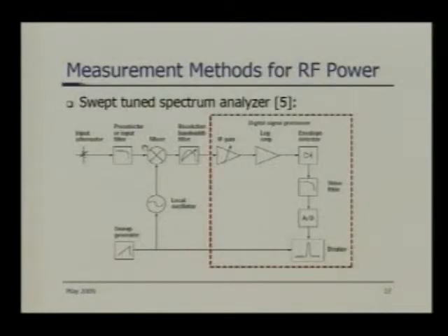There is another type, the FFT-based spectrum analyzer, but its performance is not as good. The main reason is that the input bandwidth of such analyzers is not as good compared to the swept-tuned spectrum analyzer.